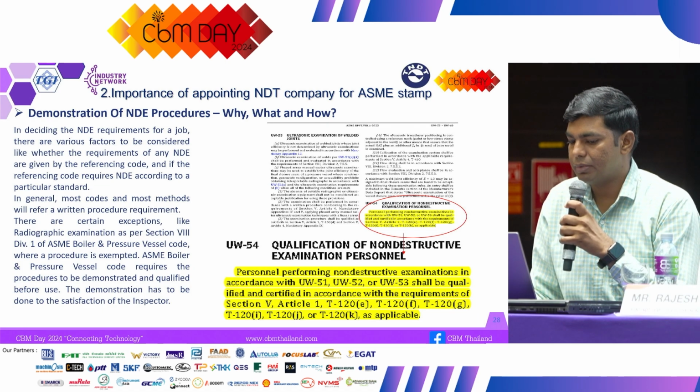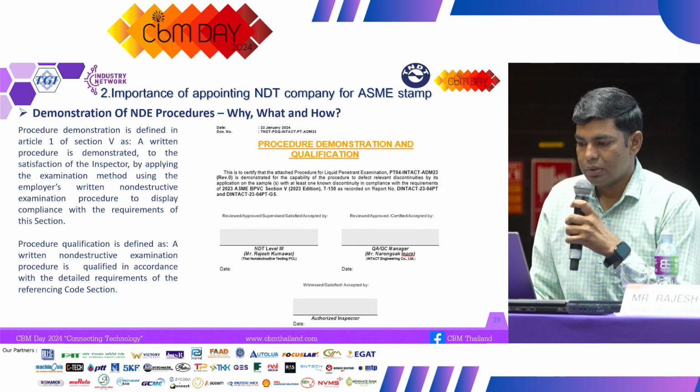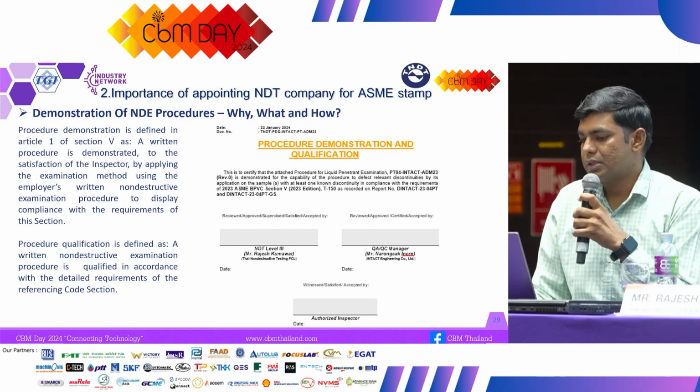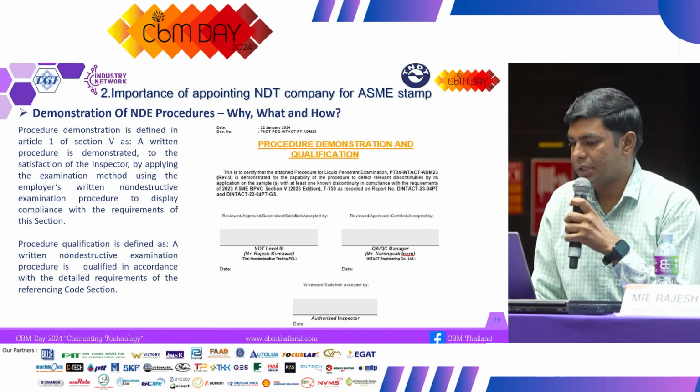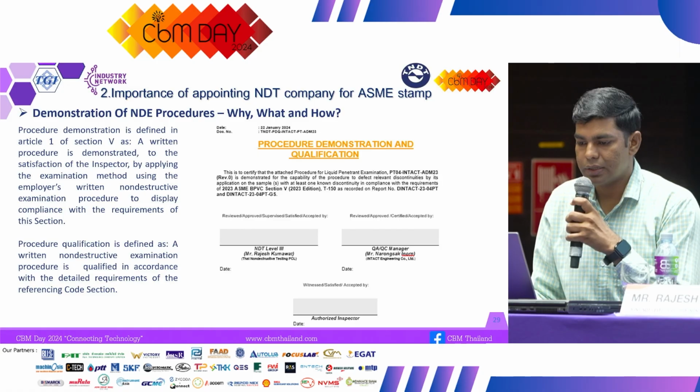Demonstrate and qualify before use. So the demonstration has been done and satisfied by the inspector. This demonstration is as per ASME Section 5. At least one specimen is needed for the demonstration, where you can see the discontinuity and identify the discontinuity.